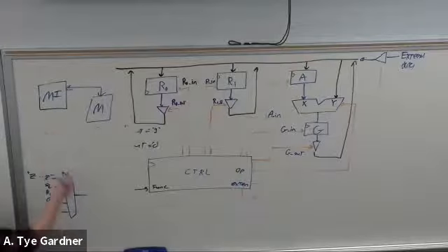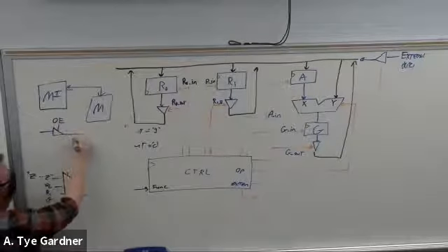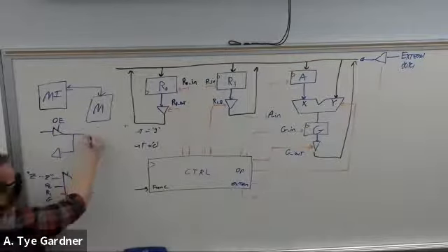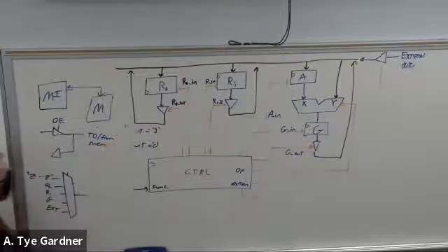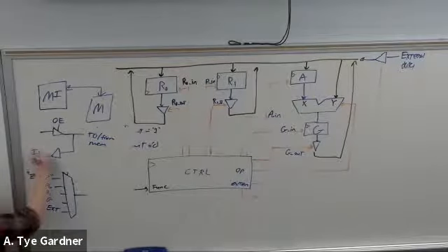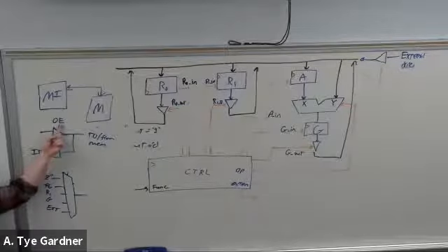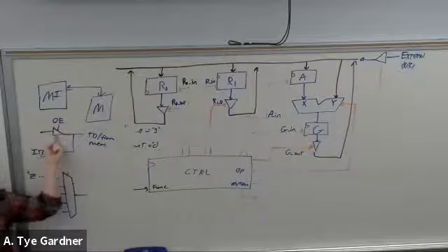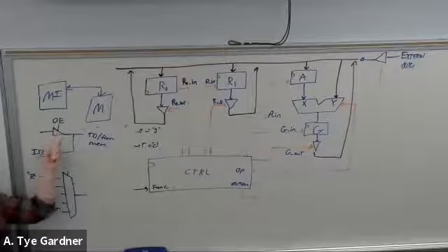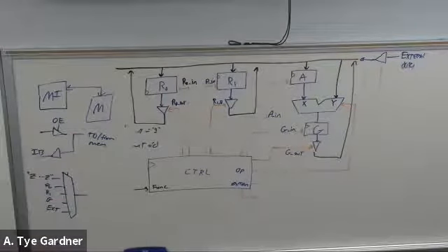And let's say output enable. This is to or from the memory, and then this is the internal bus. So what this is saying is I have some output enable. If I want to drive this memory wire, I enable this. If I want to read from it, I turn it off. If I turn off output enable, it's not connected, and it just functions as an input directly to the internal bus.